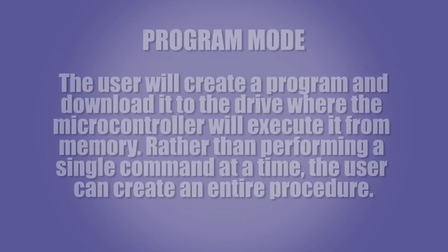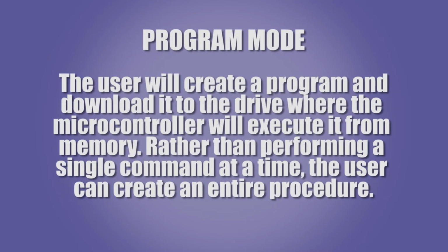In program mode, the user will create a program and download it to the drive, where the microcontroller will execute it from memory. Rather than performing a single command at a time, the user can create an entire procedure. Once the program has been downloaded, the user can then set it as a startup program where it will automatically run on drive power-up. This allows the drive to work without maintaining a connection to the PC.